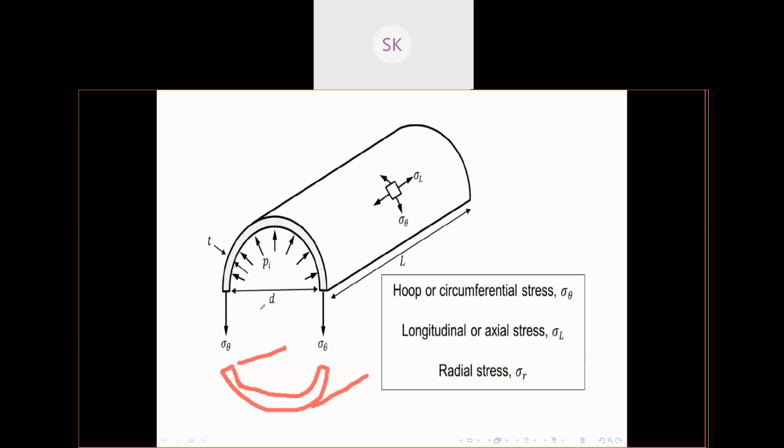We'll discuss. So when the pressure exceeds in your vessels, there will be two major ways of failure. One, it will fail along the longitudinal direction, which is called longitudinal stress, and another is it tries to break down the cylinder into two halves.